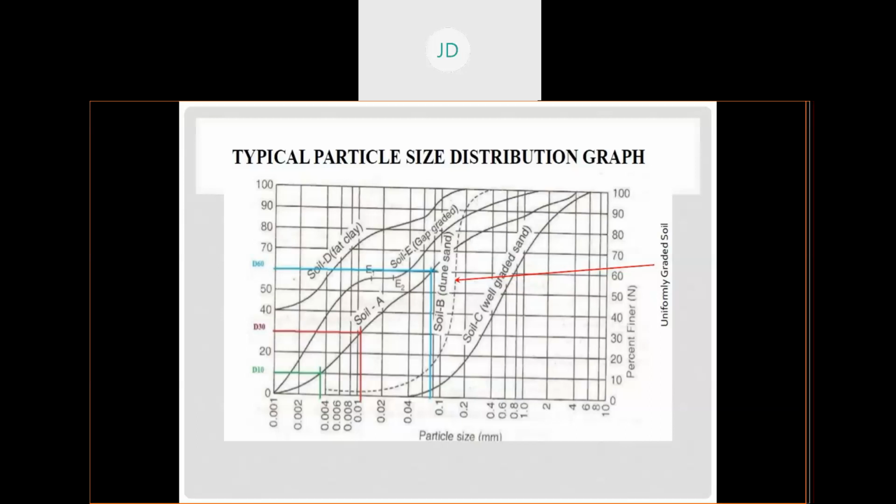Also, we have discussed different shapes. This curve can take different shapes based on different types of grade. Like this is a uniform well graded soil or well graded sand. And this is maybe a uniformly graded soil. I think it is written here, no? Uniformly graded is also known as poorly graded, you can say, since uniformly graded soil is a type of poorly graded soil. Next, it's also gap graded. Others you can ignore here for now.